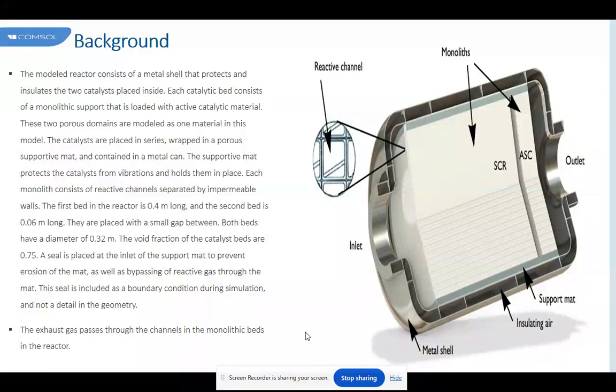The results are extended to the cases where the percentages of the transverse area given to the core and ring monolith were not even. Instead, the relative size of the core increased progressively in steps of 10% from 0% to 100%, and this simulation shows the fraction of the flow passing through the core monolith in the case where a 900 per 2.5 core was inserted in a 400 per 6.5 monolith, and vice versa.